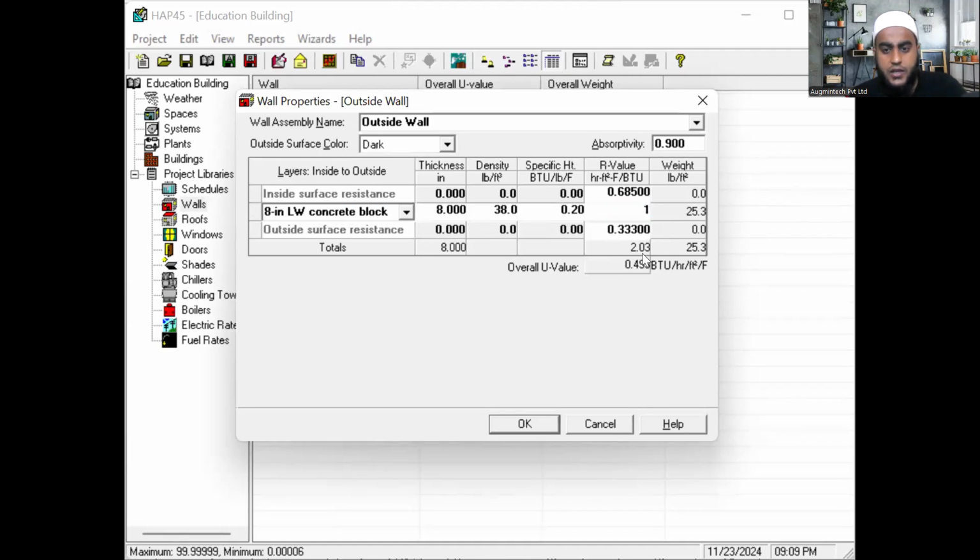Here I'm just selecting, suppose. As per that, we have got how much? 0.49. Understood? Tell me, Hassan. Clear? So you have to do the manual calculation. Actually, in designing, in our live class, we teach all this in detail, how to calculate the U value manually. If you have different types of layers, like an air gap, plaster, let's say, how much heat plaster will resist, how much the brick wall will resist. Finally, we get the U value.